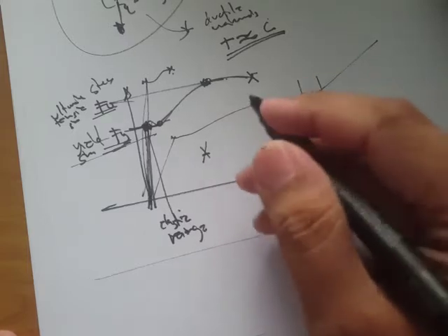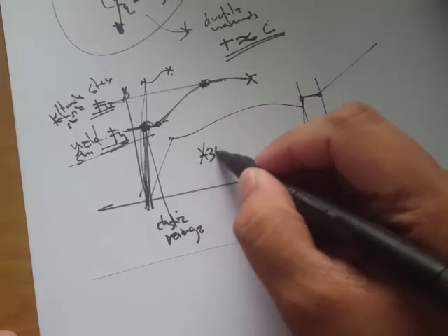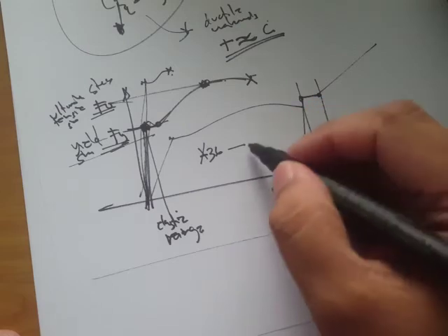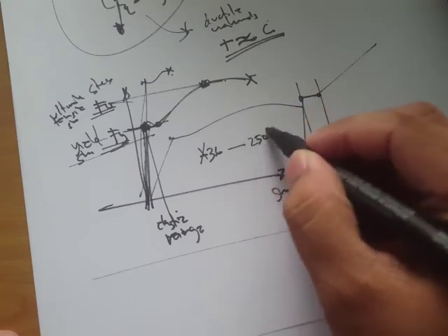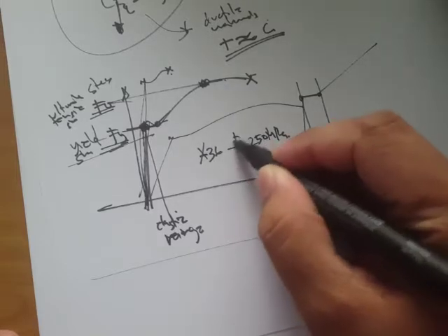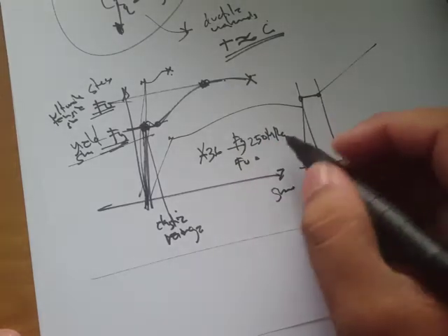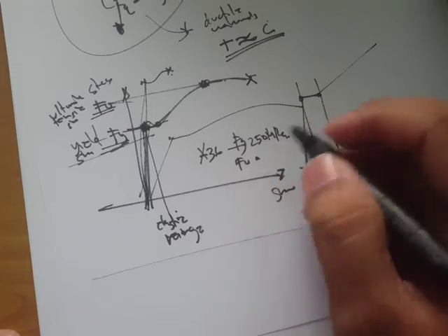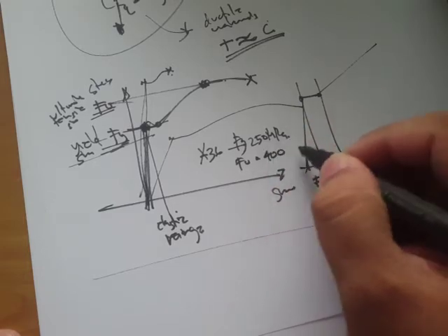Okay, so we have, for example, A36. If you look at our lecture handouts, for A36, what's our yield strength? Let's say 250 megapascals, and our Fu says 400 to 550 megapascals. So it's given in terms of a range.